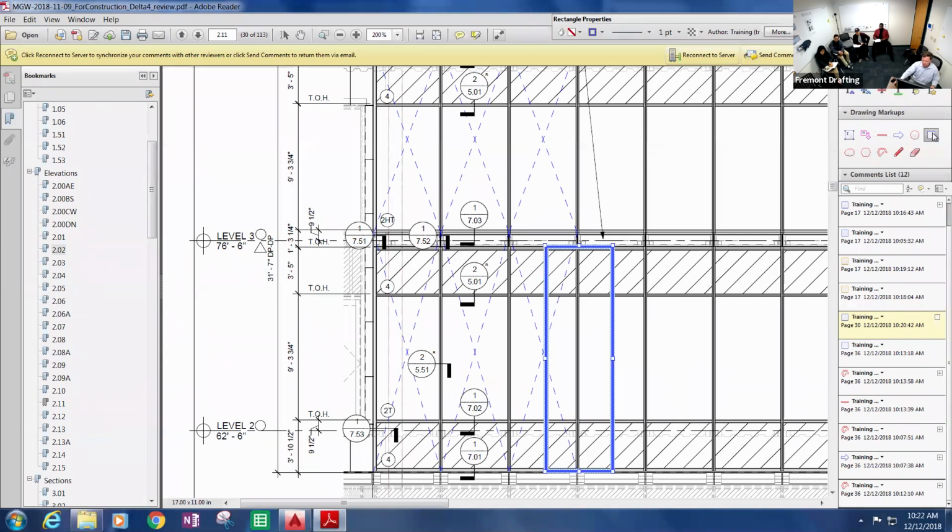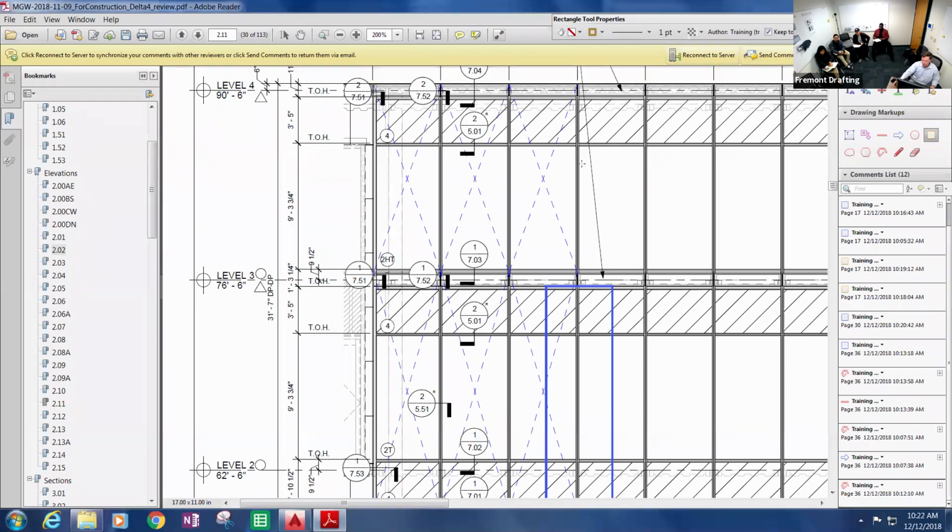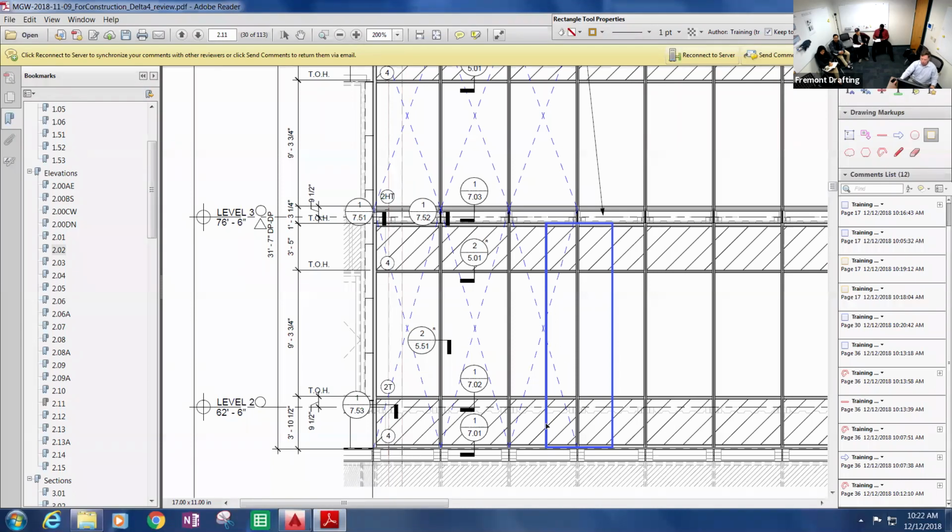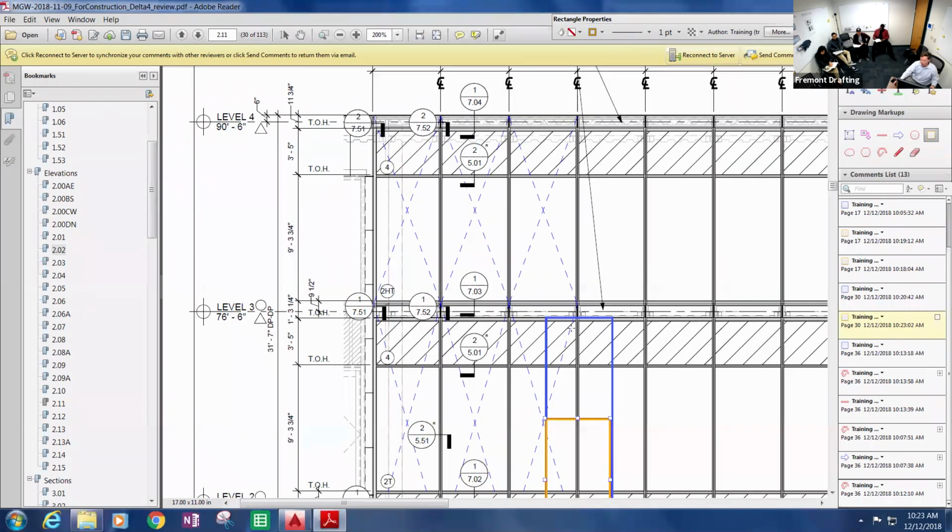And then now where it gets fun for us is going to be on the wind load. So on the wind load, on this anchor down here, it gets all the wind load of this lower half, the cantilever, but then this anchor gets half of the span up to the next anchor. So the wind load on that is going to be there for that lower anchor there.